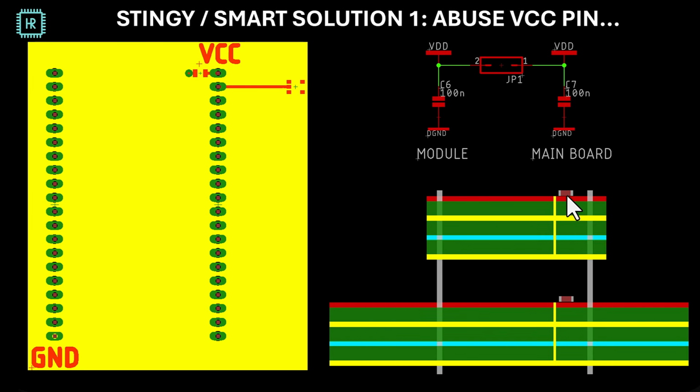I've drawn it somewhat here in a cross section, and let's assume the ground current is moving along this plane. It can go up, go through the capacitor, which is a short for AC signals, go through the connector, go through this capacitor, which again is a short, and move back to the ground plane. So that means that you're using this capacitor as an extra ground return path, or basically two capacitors and an extra ground return path. So that really halves your problem.